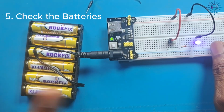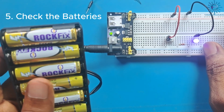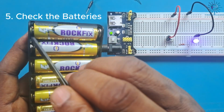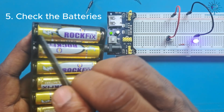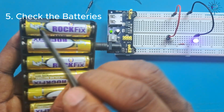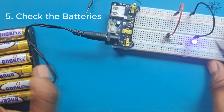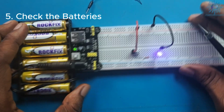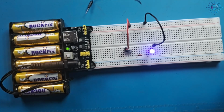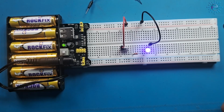Check the batteries. Make sure all the batteries are correctly inserted into the battery holder. If the batteries are inserted incorrectly, power will not be supplied to the circuit. So instead of connecting the positive terminal of the battery here, if I make the mistake of connecting the positive here and the negative here, and if I do it for all these batteries or for most of the batteries, we will not have the required voltage in our circuit and our circuit will not work. So these are the few things you can check to troubleshoot and fix your circuit. You should be able to identify the problem and get your circuit working.